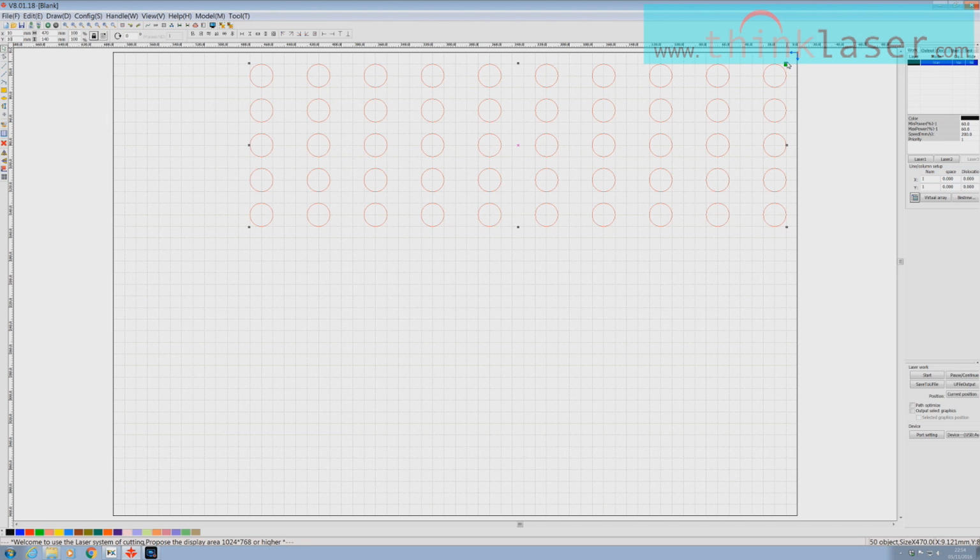Okay, so now that we've accurately positioned that corner, we can see that every one of these intersections is coinciding with the center of a circle. And of course we can just count these, because I know that I made these 10 millimeter pitch. So that's 1, 2, 3, 4, 5. Yes, so we've got our 50 millimeters. But is there another way of doing it? Well, the only way that I can check two of them now is to say, well, 50mm centres plus 10, so that's 70mm, the length of that side. And sure enough, look, it says 70mm.